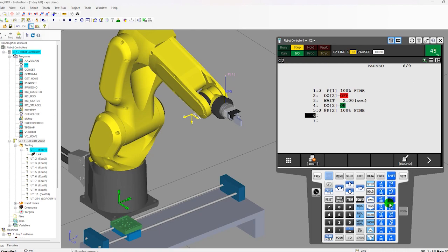Then here you can use these buttons to control the motion of these joints. For us, we have 6 joints. They have 8, right? So for us, we only have 6. But before that, you need to make sure what kind of coordinate you are using. Remember, in the software, we can choose Cartesian coordinates or joint coordinates. Similarly, on the teaching pendant, you click the coordinate to change it.